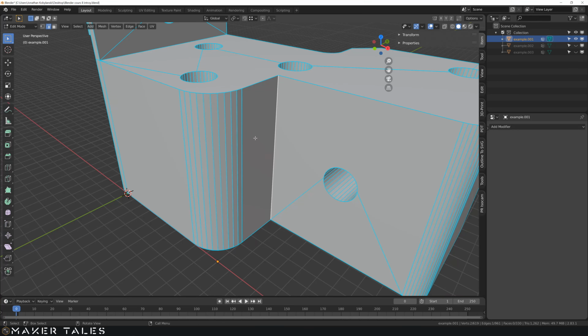So if we go ahead and add this bevel here, the way I go about undoing a bevel is I'm going to show you a new selection technique here. So we have one edge selected, and then if you hit C, you get something called the circle selection. And if you use the scroll wheel, you can increase the selection area. You can't move in this mode, but it lets you select a lot of things very quickly. And to deselect, you use the middle scroll wheel button, so the middle click.